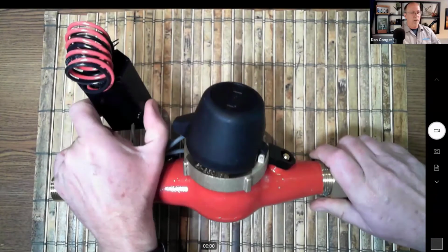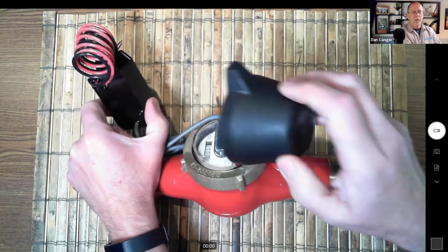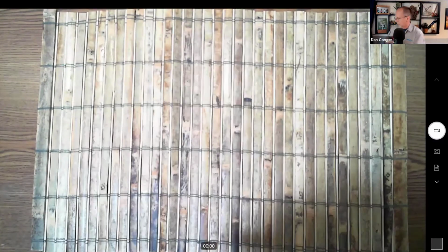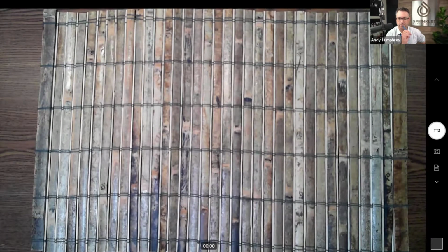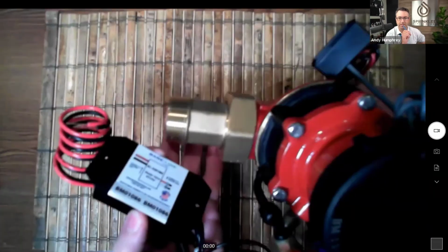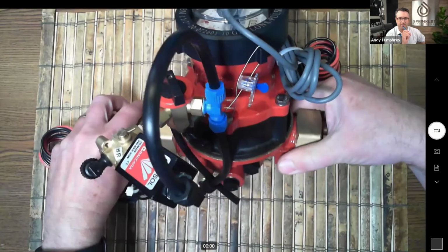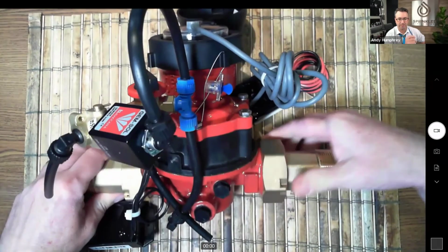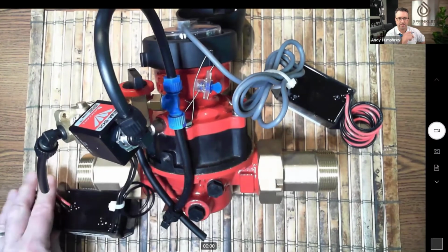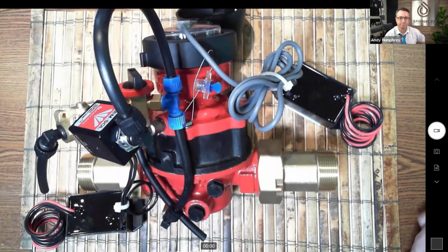Nice. So on this meter design with this register, I've got a beast here. Give me just a moment, I'm going to bring that one over. Yep. And while you're doing that, that particular meter head, I believe, is called a photodiode. There are multiple meter options. So if you have an existing meter and you want to retrofit it to a baseline system, we do recommend the photodiode output meter head, and they can easily be replaced. You just unscrew that black cover, and that meter head just pops off and it's completely sealed, so it's not like anything leaks out. It's just sitting on top of there magnetically.